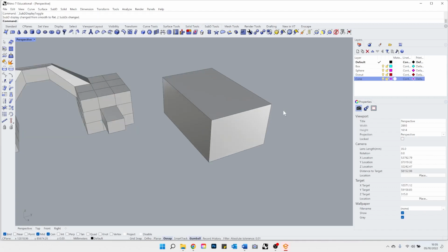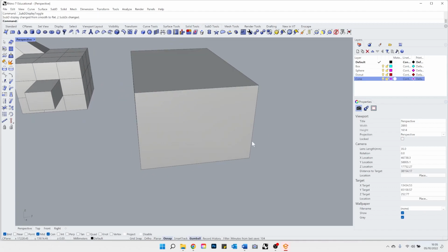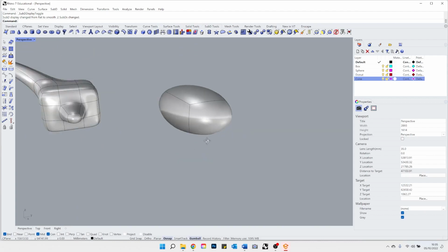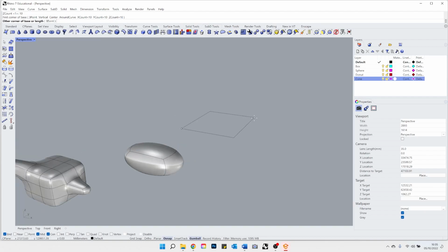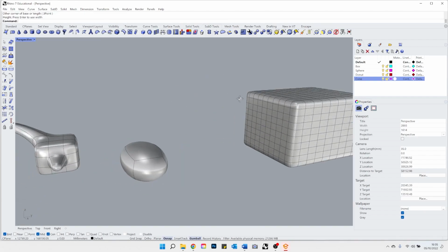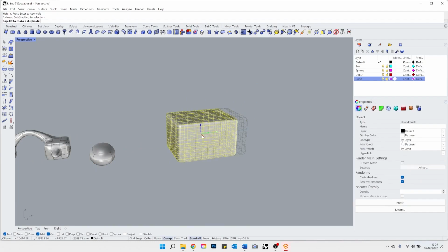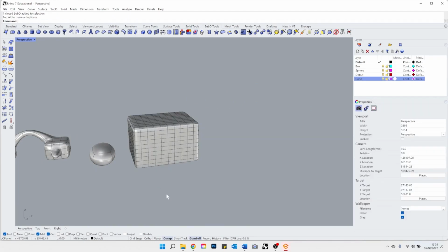which in a normal, rigid view is going to look like a normal box. But if I click tab again, it's almost starting to look like something sphere-like. But if I create the same box using a larger X count, Y count, and Z count, so for example, 10, 10, and Z count 10 again, it's the same box, but you can see the difference. It has more polygons trying to keep the shape as it is.